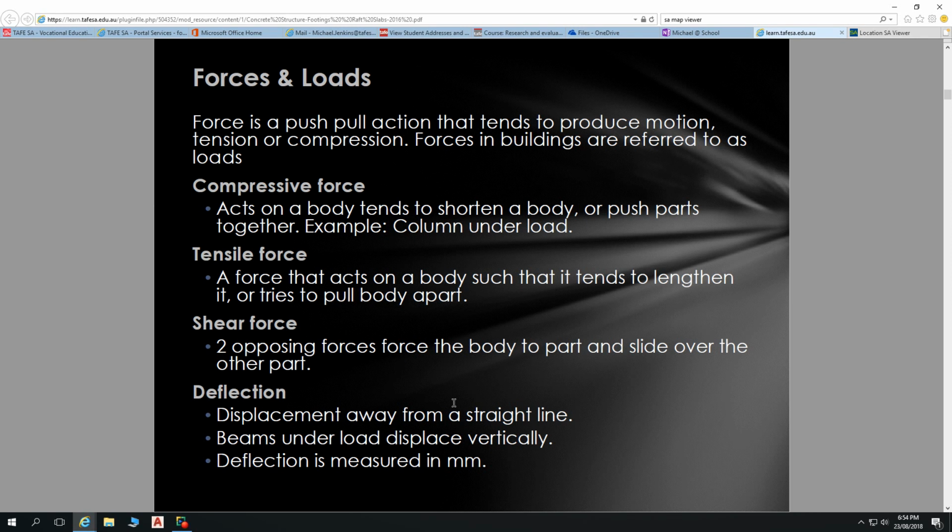So our top plate's running this way. Our truss is doing that. So we fix our top plate there to our truss, but if we look at that in elevation, this is our fixing plate, our L-shaped fixing plate there. We have elongated nail holes like that. So this plate is nailed straight through there, but it can move slightly.